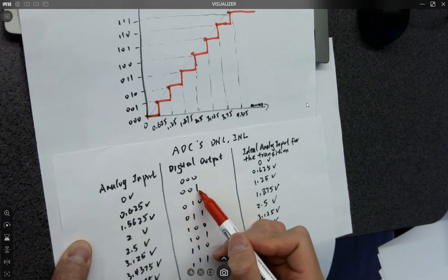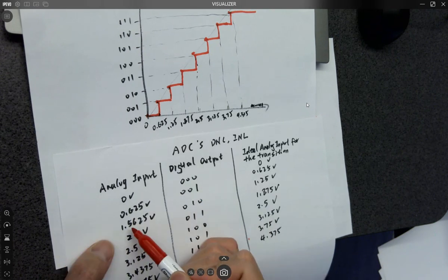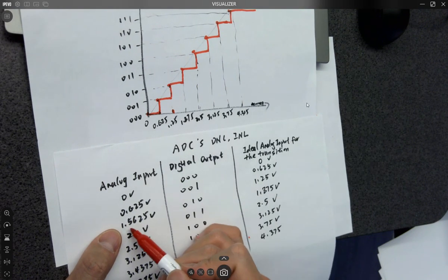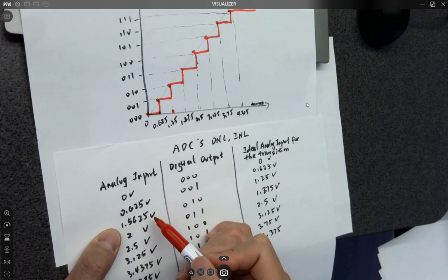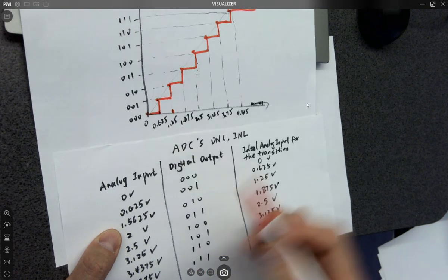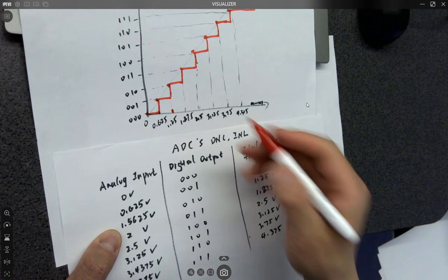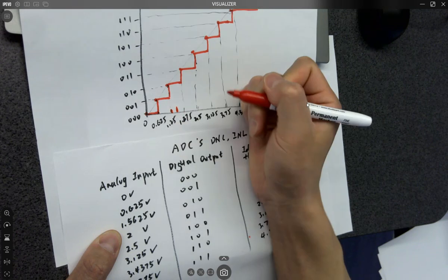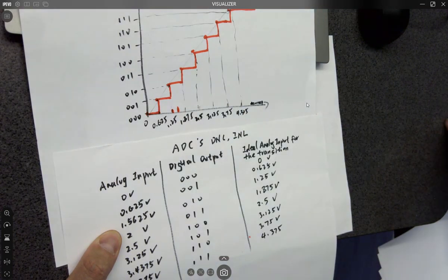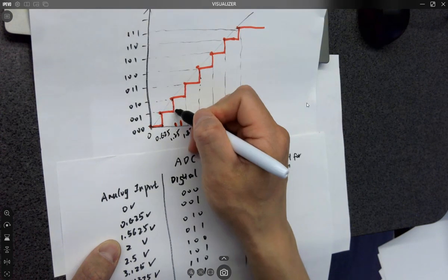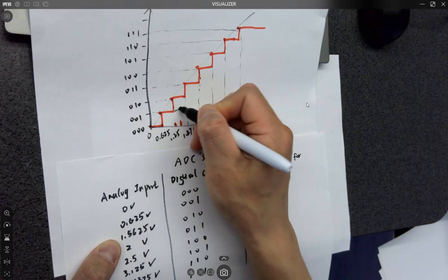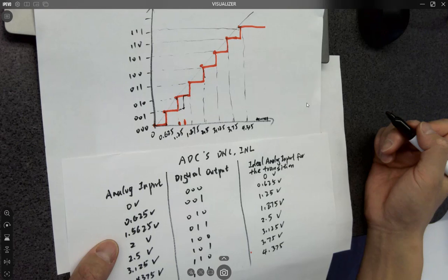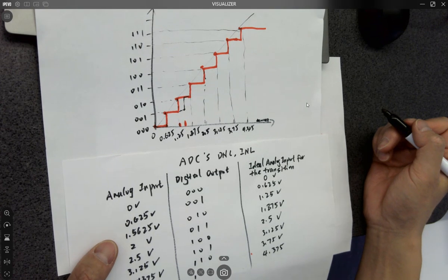0.625 is 1 LSB. It's getting 1 LSB, no problem. And 1.25 is giving you 2 LSBs, but actually it waits until 1.5625 to jump to number 2 instead of 1.25. So basically, it's not jumping at this point; it's jumping at this point. Okay, so on the curve, it looks like this. It's actually extended to here and then jump. So it generates a DNL here.